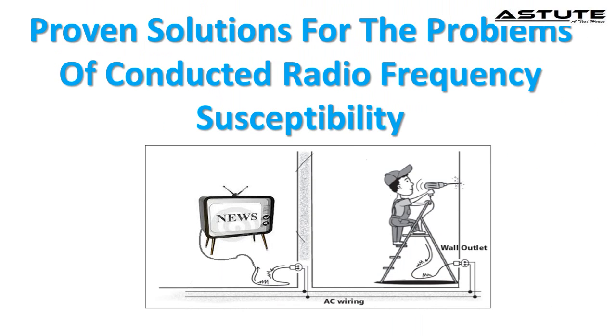To remove or minimize conducted RF noise from the device, the following tricks are very important. The most effective method for reducing conducted emissions is to suppress them at their source. Use proper line filters. Shielding is important. Also, proper grounding at the required places is most important. Increasing the value of the gate resistor RG in the primary side switcher will increase the rise or fall times of the switching waveform and hence reduce their spectral content.